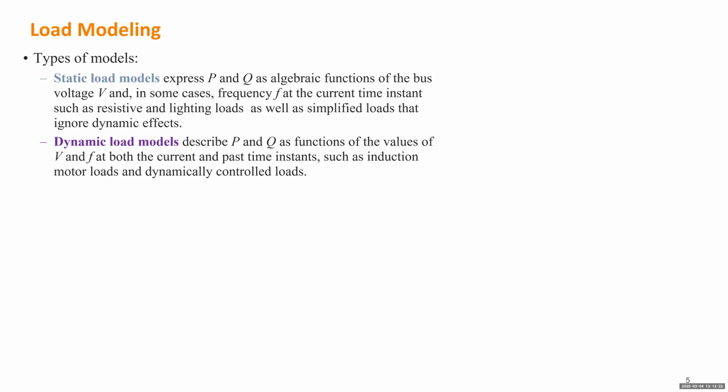Okay, so it may integrate some differential equation. By solving the differential equation, you can have the trajectory of the load, and then you'll find the current time instant that will tell you the more accurate information. So in such case, such dynamic load model can be similar to generators. Like a generator is not a static device, it's a dynamic device. So that's why usually the representative dynamic loads are motor loads, like air conditioner or with some industry.